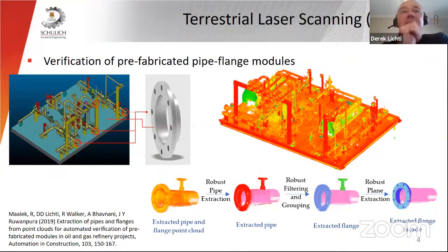And so they want to scan this prefabricated module in the works yard and then determine dimensional compliance. And so that means collecting the point cloud on the top right, which is really a jumble, locating each of the flanges, basically the point cloud around the region, and then performing some identification processes to determine the front face of the flange, so the plane, and then the cylinder. We can intersect the end axis of the cylinder with the flange and get the position. And once we have this for all of the flanges, then we can make that decision whether or not the assembly is dimensionally compliant.